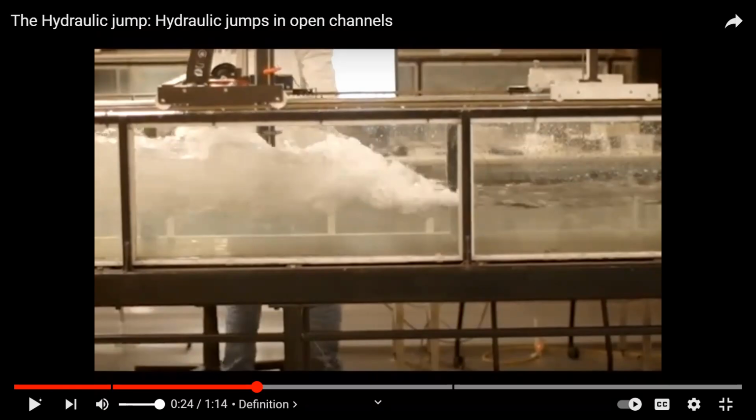So it jumps, and during this time, the flow velocity starts changing rapidly. So the flow becomes turbulent and it reduces the energy, head loss. After that, when the water flows again, the flow has become normal. In other words, it has become subcritical flow.